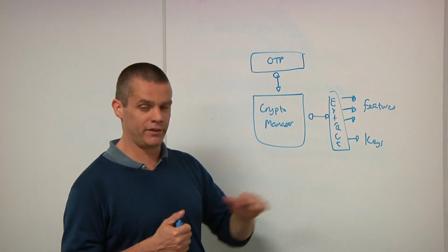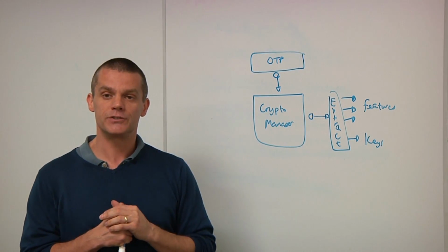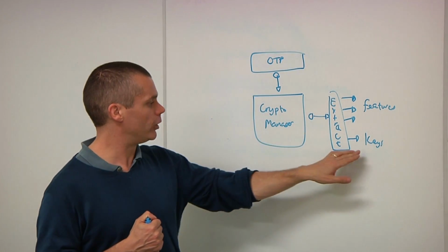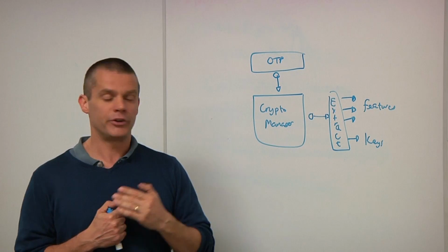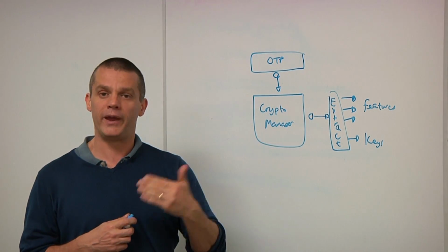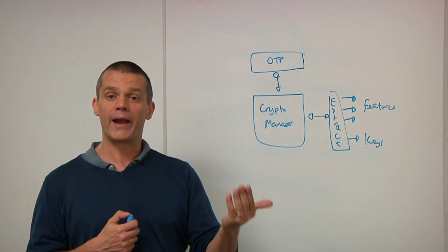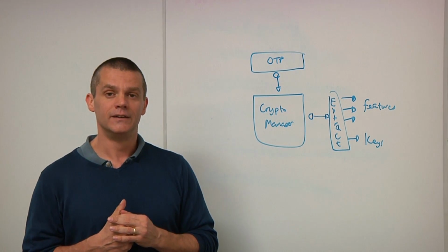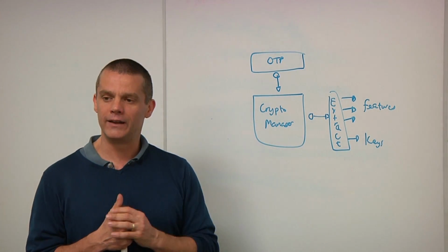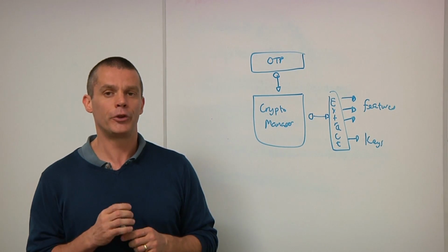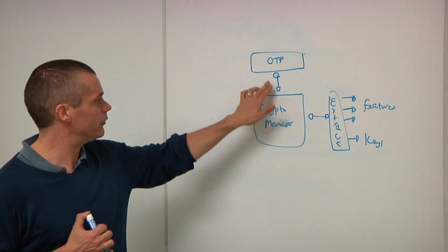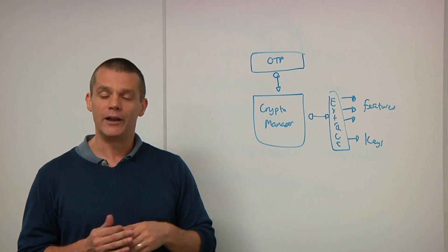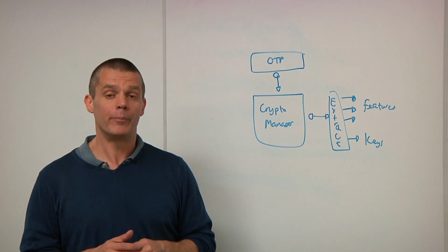The second kind of use case is around providing keys to applications. How would that work? Well, there's a couple of ways you can think about doing this. One of the options is to think about the root of trust as just being a key service. So you've got your bank's payment application running on your device. It needs to establish a key. Now, if you just send that key in the clear to the device, there's going to be a security problem. So what you can do instead is bootstrap the key that you've provisioned into the device during manufacture and use that key to now load the key that the bank wants.